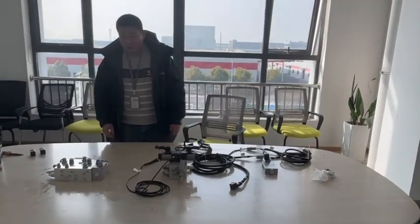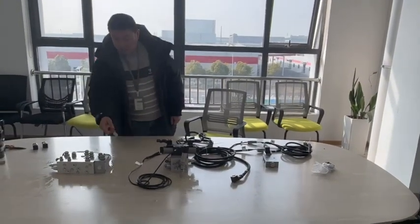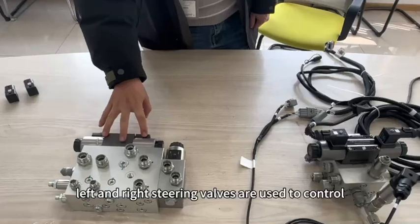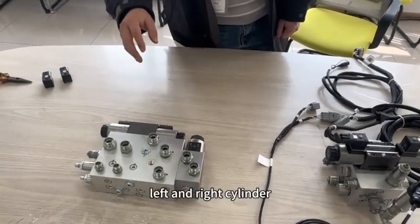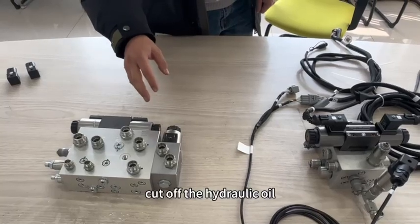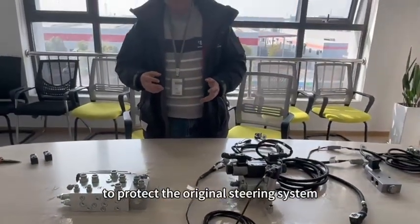Hello guys. Normally we need to collect and control 3 valves to achieve automatic drive: cutoff valve, left and right steering valve. Left and right steering valve are used to control the hydraulic oil going into the left and right cylinder. The cutoff valve is used to cut off the hydraulic oil from the electro-hydraulic valve to the orbital valve to protect the original steering system.